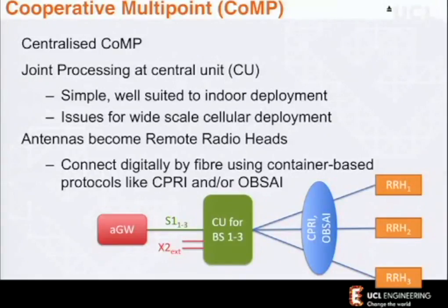So again, we now actually have remote radio heads transporting, whether analog or CPRI. Now in front of our gateways, we can do some of this co-processing. And we're at the same point. We're receiving these signals. We'll have to factor out differential delays between these, but we can; PON systems do training of optical links down to 32 nanoseconds.